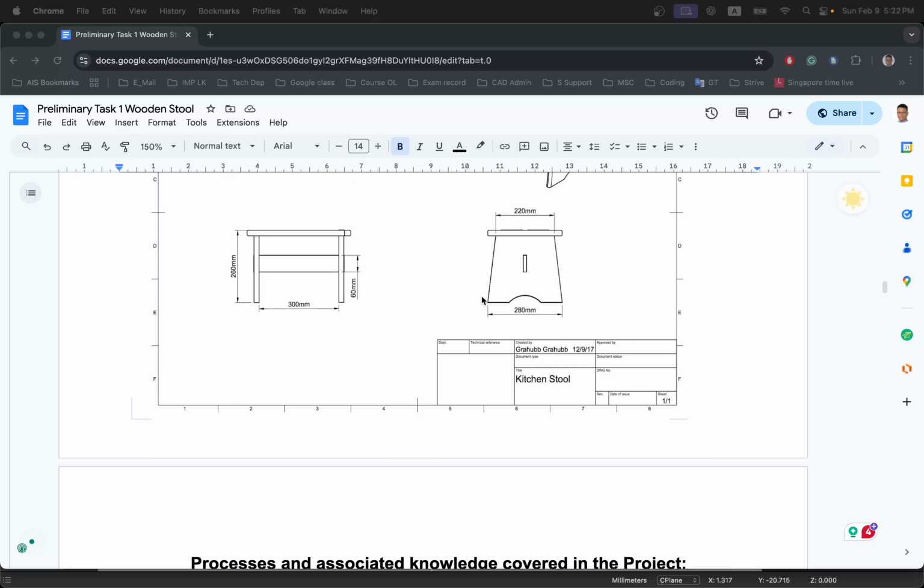To navigate this interface, always make sure that you have turned on the grid setting and the gumball. And make sure that the persistent is always activated with end, near, midpoint, intersection, and coordinates turned on. Those are the basic setup when you just start the project.